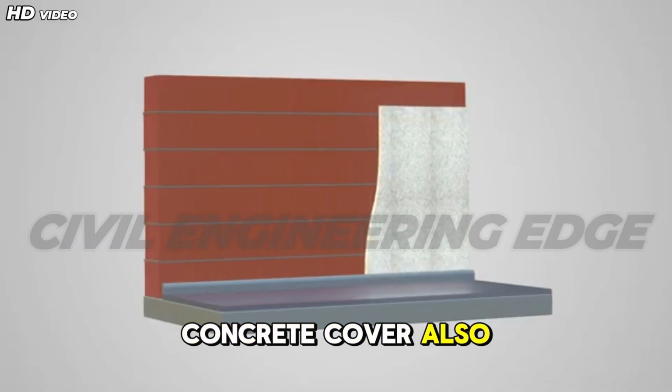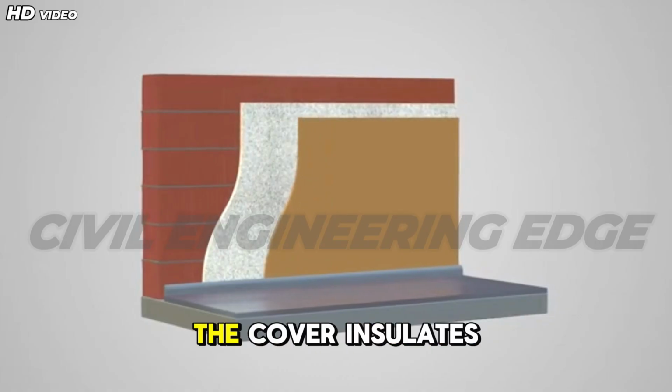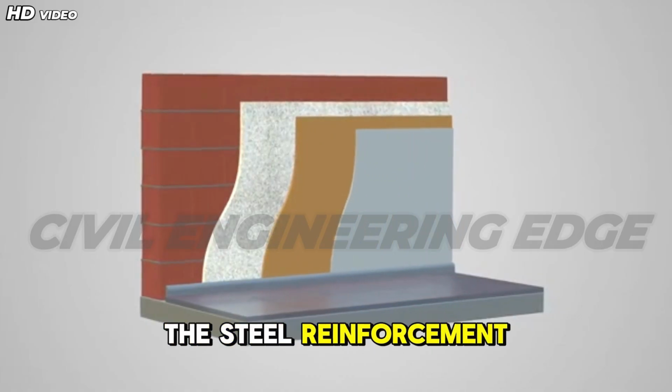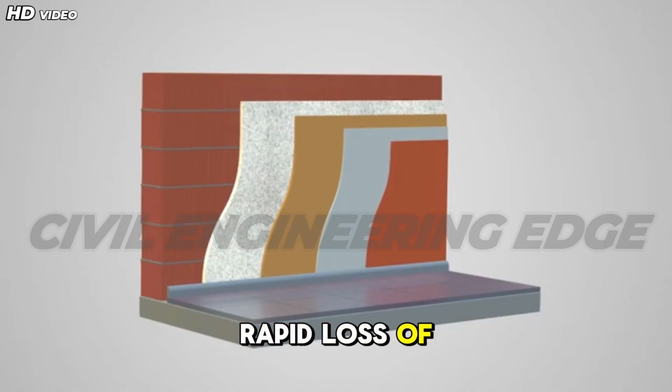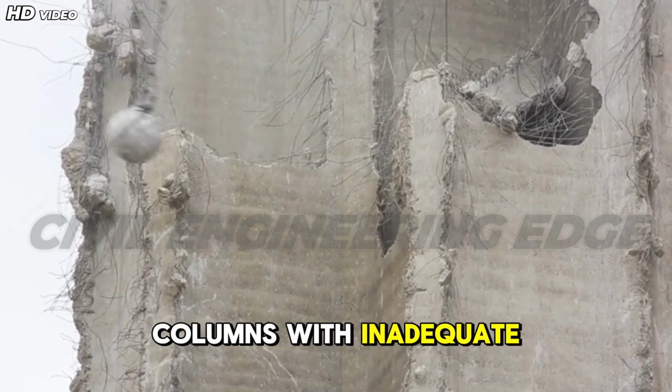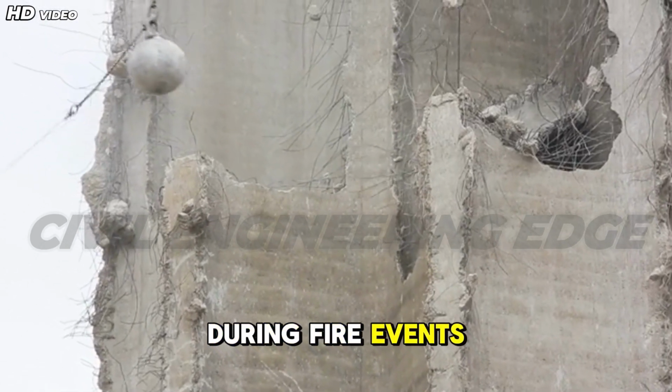Concrete cover also contributes to fire resistance. During fire exposure, the cover insulates the steel reinforcement, delaying temperature rise and preventing rapid loss of strength. Columns with inadequate cover may experience premature failure during fire events.